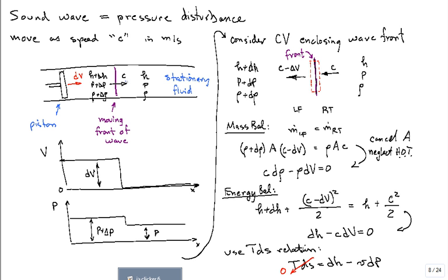All right, so now that pressure pulse travels at a sonic speed c, where the fluid over here is stationary and doesn't know that the piston over there moved. It doesn't know my tongue moved yet until it gets to your eardrum, and then, oh yeah, he spoke. Okay, so it's quiescent, it's at enthalpy, pressure, and density, but behind it, it felt the effect of that change in the piston velocity, that abrupt pop. And it has a change in enthalpy, the pressure is P plus delta P, and the density is rho plus delta rho.